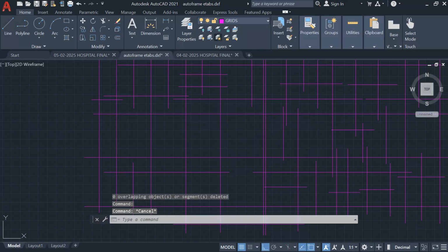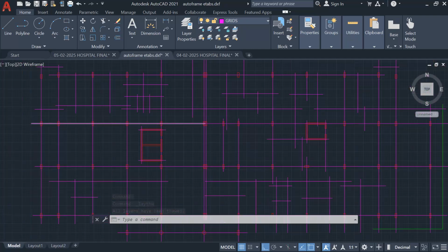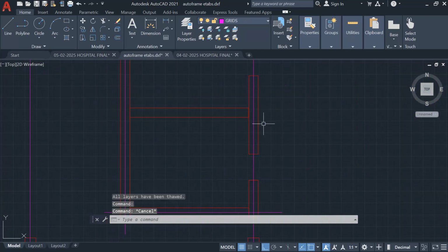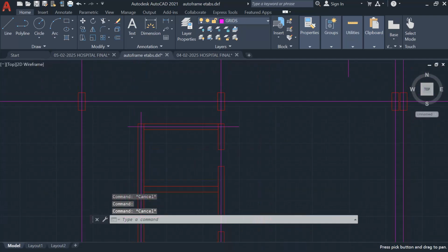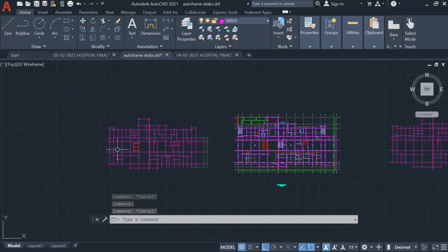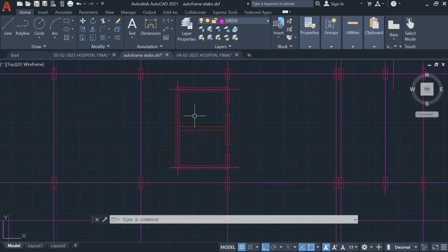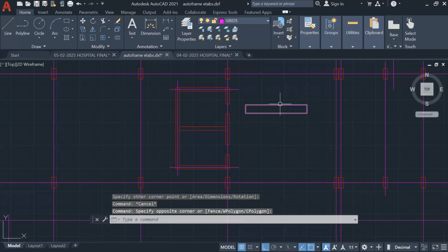Once you turn on your columns here, you're going to have something that is exactly like this. It's important for you to understand that for these shear walls, you're supposed to define them like this as separate shear walls. How? This is just by drawing rectangular shaped shear walls here using this command that is normally here. Just draw them like that. So that's how you achieve that.